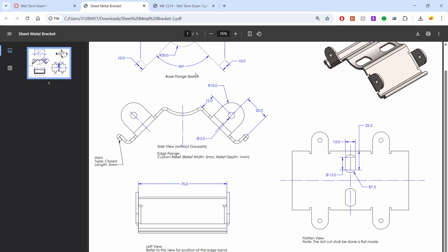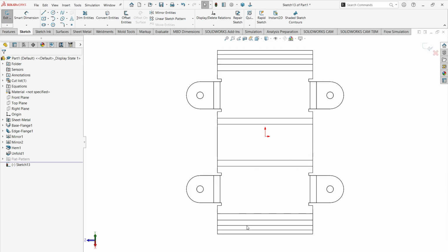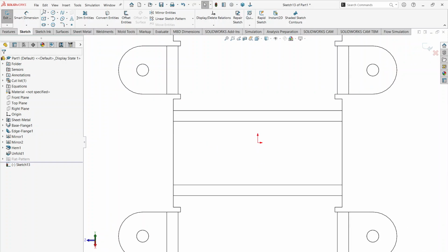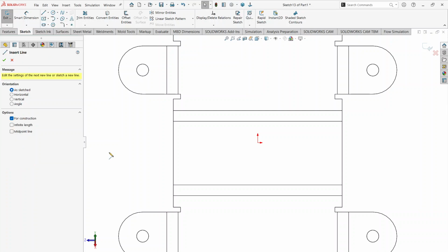The information for the cut is according to here. So first I have to put it exactly in the center point, and then it has a two-slot cut that you have to create. If you see, this does not fall necessarily in the center of this, so an easy way is I'm going to go to the center line and hover around the center point.